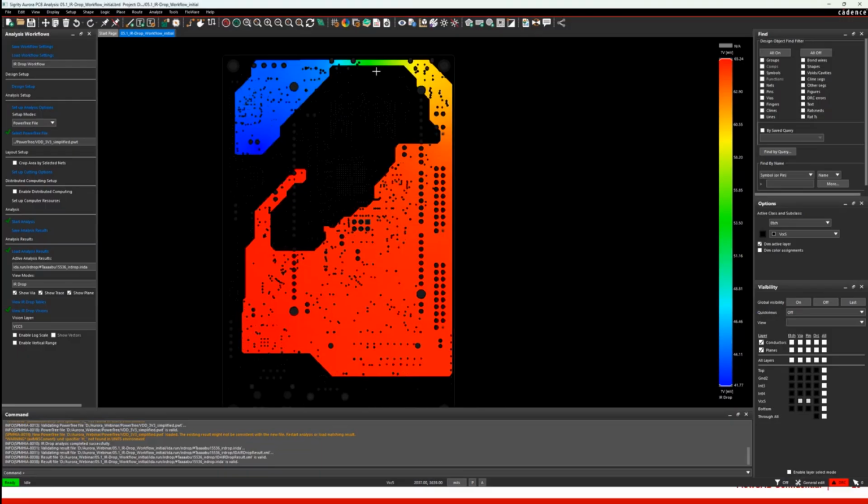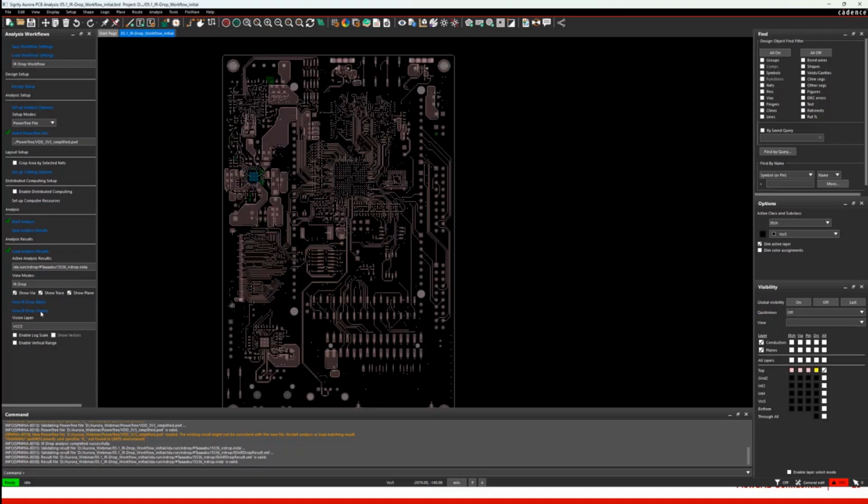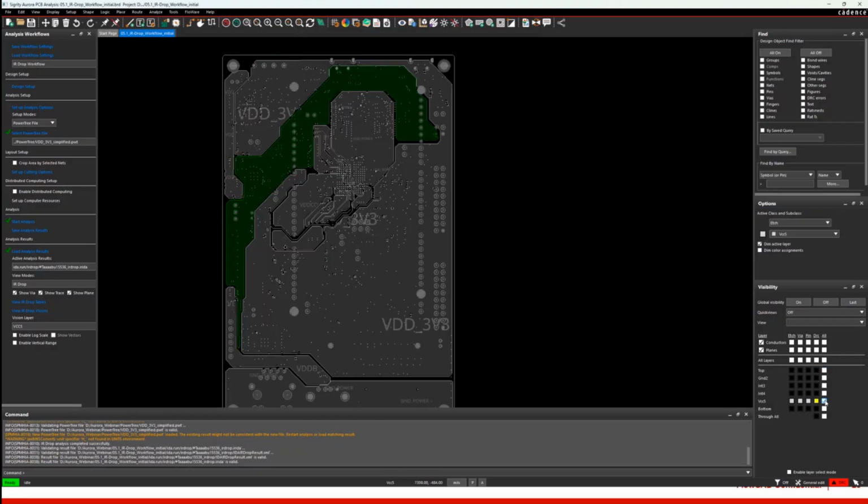And here we can see a very small path where probably the high voltage drop will be created. Once you do not have this, and we only have to do such analysis in a layout review, you may see, okay, here this is our 3.3 power rail, but it might be very difficult to identify that this region creates such a big voltage drop.